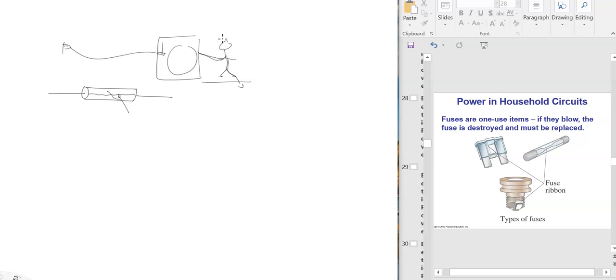I'm just adding some stuff, that's some safety advice here. Sometimes, not everybody, but some people, because they are lazy to go to the hardware store and buy a fuse, once the fuse blows up, they'll replace this wire with some piece of wire they can find around the house.